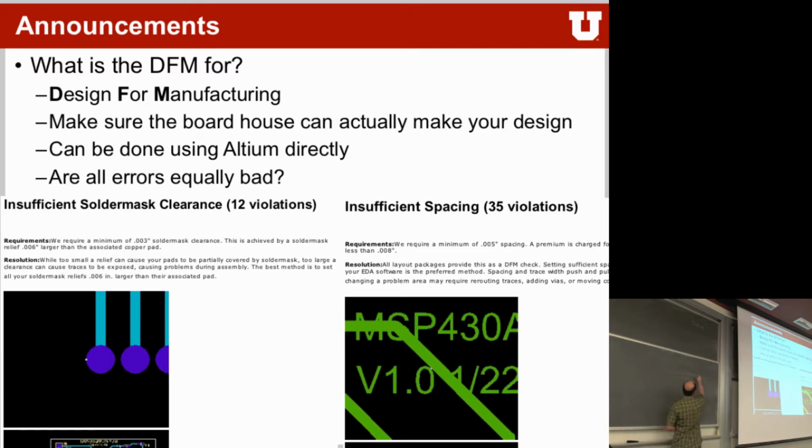Now, if we have a hole somewhere that we want to solder to, you preferably want the solder mask to stop before the hole. Or else, it could happen that this solder mask goes on top of the hole and it does something like this. And this is not very good because this can then lift off and the solder mask can come off, and they don't want that. In addition to that, we now have this gap that you have to fill with solder, and sometimes you have to go inside of it, also not very good.